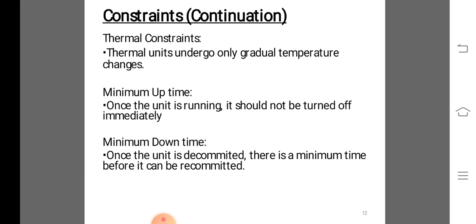Not only must the reserve be sufficient to make up for a generation unit failure, but the reserve must be allocated among fast responding units and slow responding units.